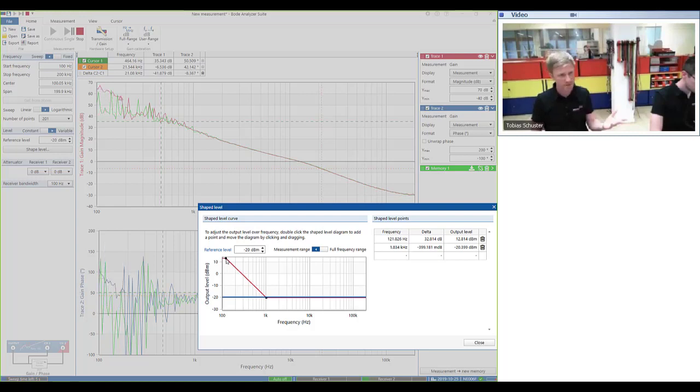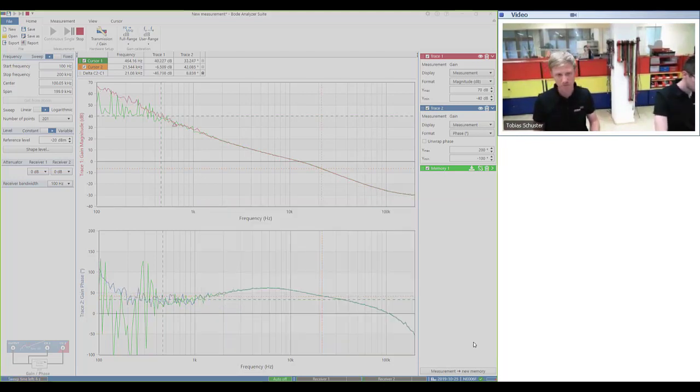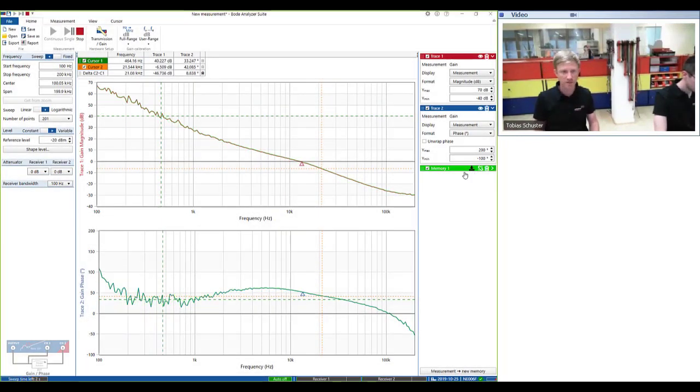And at low frequencies the system is not sensitive to the signal level size. Yeah, at DC you can change it from anywhere to anywhere. At low frequencies there are no slew rate limitations or others. So now I close and I update the memory here, and now we have a measurement that runs from roughly 65 dB to minus 30 dBs, so nearly 100 dBs of range, and it runs in 5 seconds. It completes the sweep, and that's pretty nice.